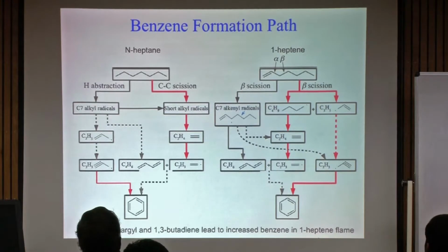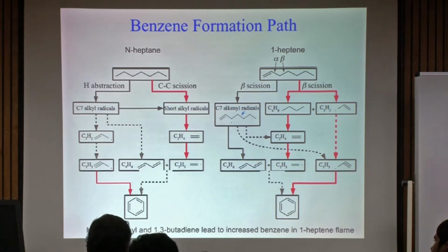These are some details. I will skip this, because the student was doing his PhD work, so he looked. Also, Chemkin has this capability. You can look at the reaction path analysis. So you can look at the individual species. You can choose one, let's say acetylene, and see where this acetylene comes from.